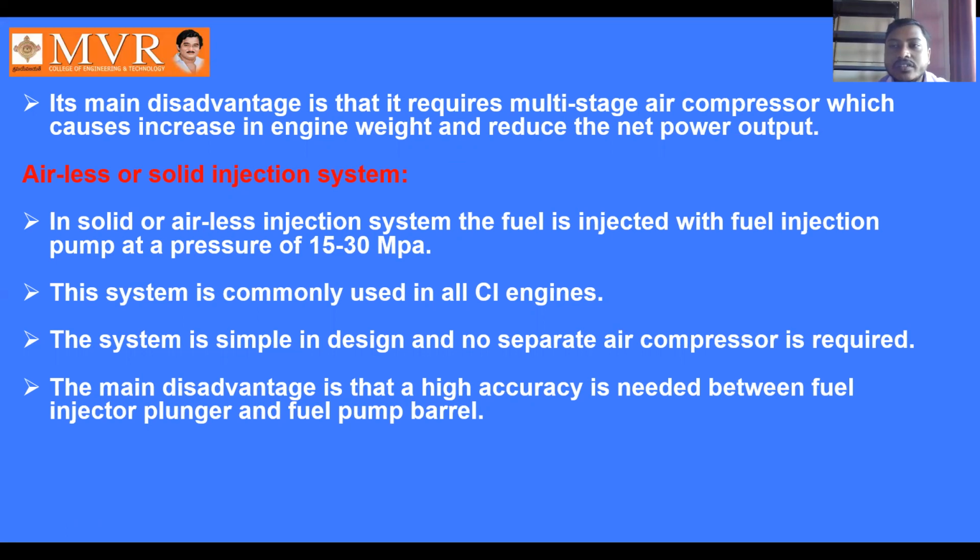The main disadvantage is that a high accuracy is needed between the fuel injector plunger and the fuel pump barrel. Here we need a high-accuracy fuel injector plunger and fuel pump barrel in the solid injection system. This is what we have about the airless or solid injection system.